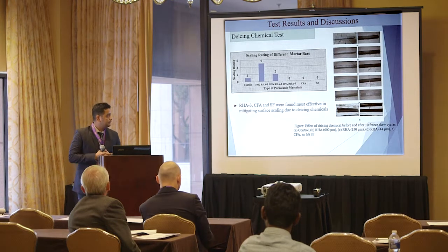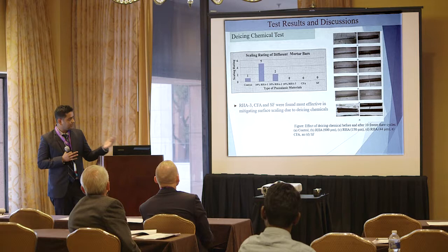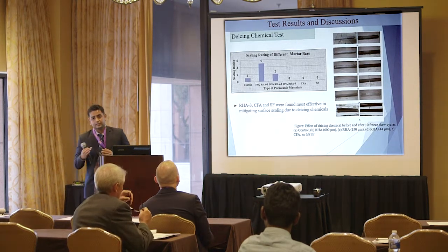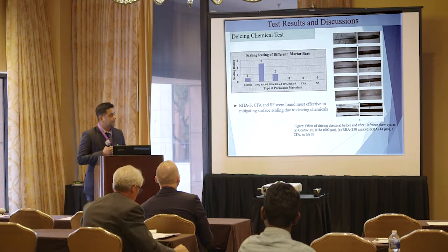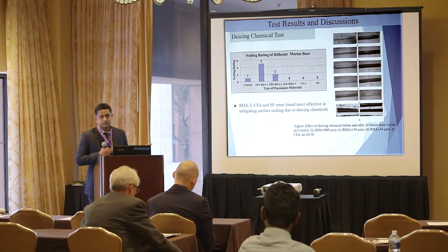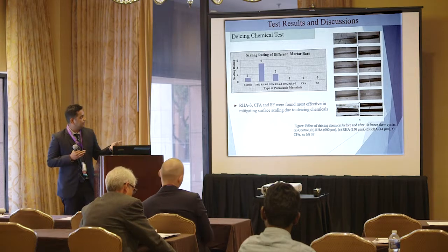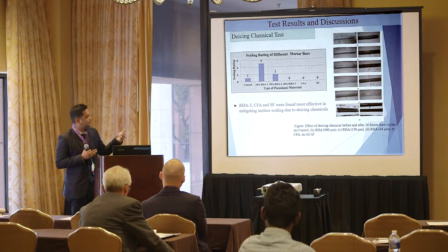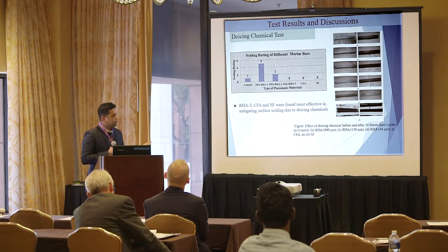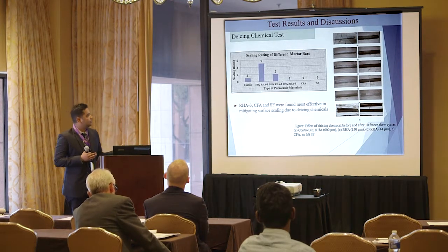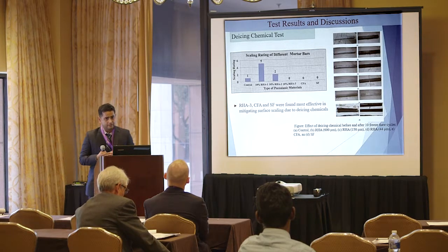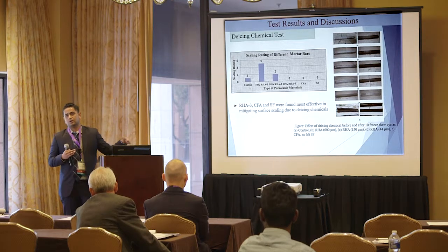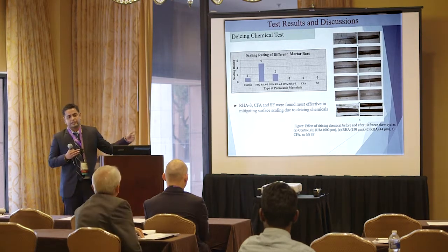And there is a very interesting outcome: RHA3, which is the finest RHA, shows very little scaling on the concrete mortar bar surface. And I rated them. You can see from the graph that RHA3, CFA and silica fume have a 0 marking on the scaling rating. And in this experiment, there are 10 cycles of freeze-thaw.